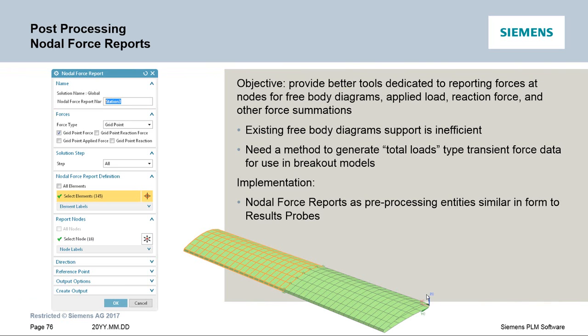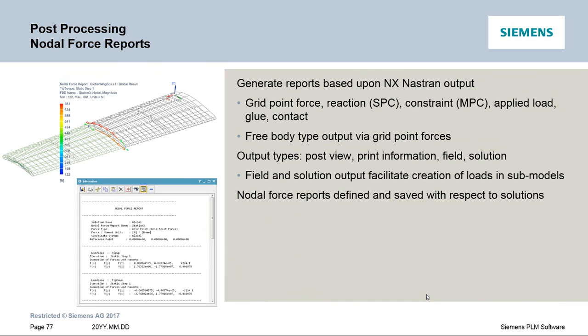We also have new capabilities for post-processing nodal force reports. And this is to enhance the free body diagram capabilities that existed previously. We have the ability to specify the nodal force reports in the preprocessor and then be able to plot them very quickly and easily without having to go to post-processing and define a free body each time.